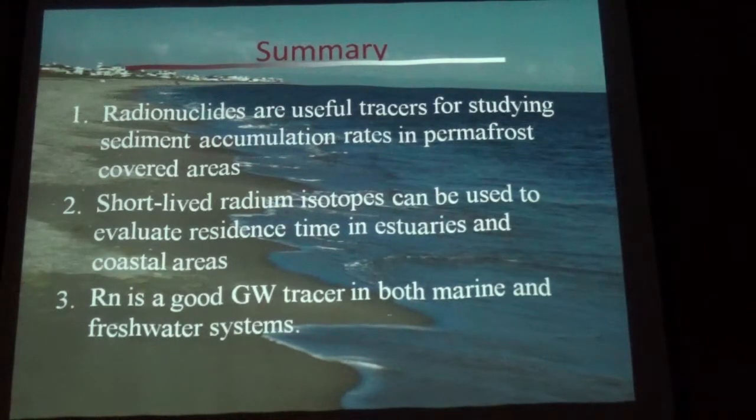For my dissertation, I worked on lakes in central Florida and the method was found very useful. For 2 years, we screened 7 lakes. We did a seasonal study in 3 of them, which is quite impressive. It's a non-invasive technique. You don't go and drill wells there. You basically deploy your system, measure it for some time, perform the mass balance, collect some sediment for the lab, perform the diffusion and mass balance, and calculate discharge, which the local authorities found very attractive, and eventually they would implement this as a regular monitoring technique.